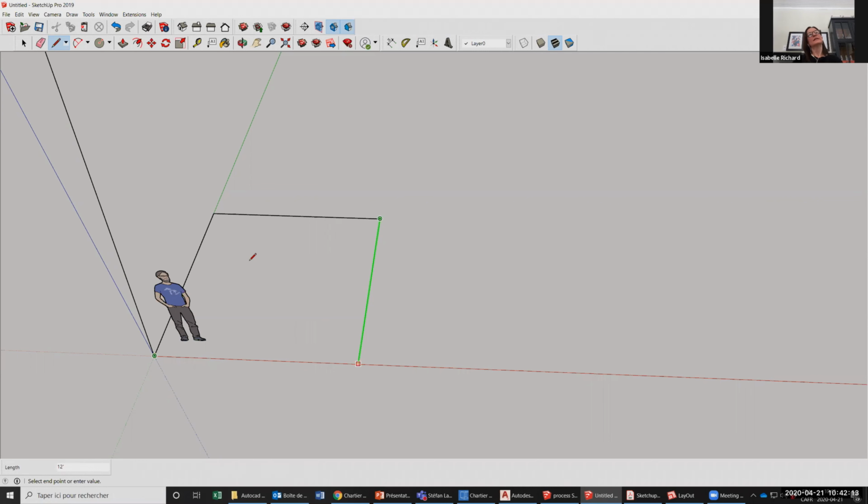See, every time you go near an end point of your segment, there's a green dot that appears. So it shows you that it's one of the principal points that you can refer to. There's also the midpoint that you can go to, right? I want to go to the midpoint or the end point. So let me go to the end point.